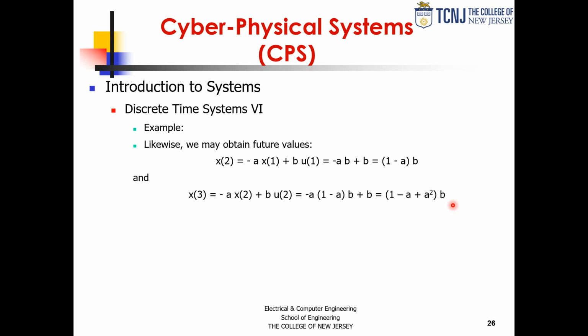Under certain conditions, if the system is linear, time invariant, and we're also going to talk about the system being stable. The system has to be stable in what we call the BIBO sense: bounded input, bounded output. What that means is that if I put a bounded input into a system, so my input is bounded by two real values, I'm expected to get some type of output that is also bounded. Not by the same values, but bounded. That's important. So my system is stable.